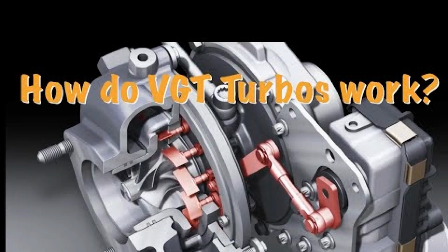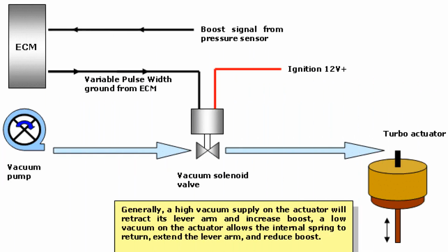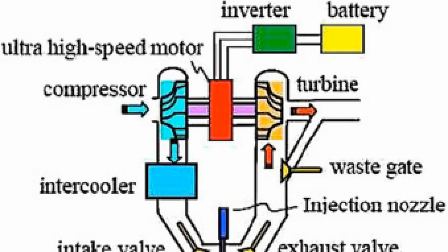Overspin zone. The design of the turbocharger suggests efficiency zones. The engine is also designed for a certain amount of boost. If the exhaust gas flow rate exceeds the optimum efficiency zone and the design boost value, further use of the turbocharger will only reduce engine efficiency. Also, exceeding the design impeller speed leads to airflow stall. That is why most turbines are designed with a valve that bypasses the turbine wheel at certain engine speeds.